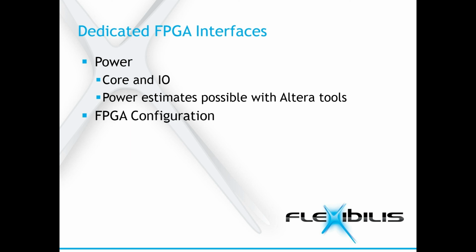The FPGA configuration is volatile, and therefore the configuration bit stream has to be loaded onto the FPGA after every power-up. There are several different ways to do the loading of the bit stream. The FPGA can, for example, fetch the configuration bit stream automatically from a dedicated configuration flash chip. Another alternative is to do the writing of the bit stream to the FPGA by an onboard CPU.